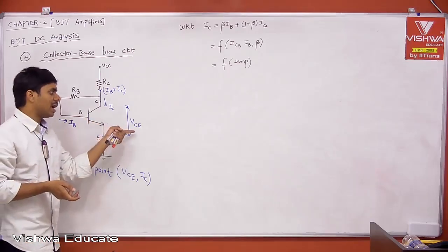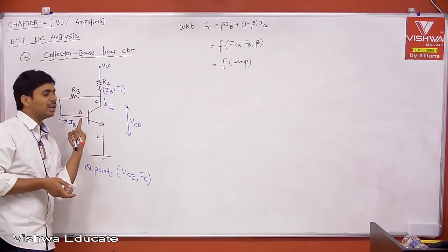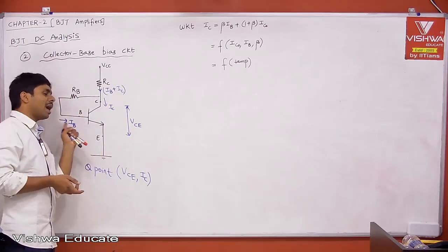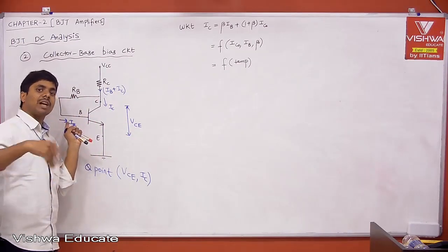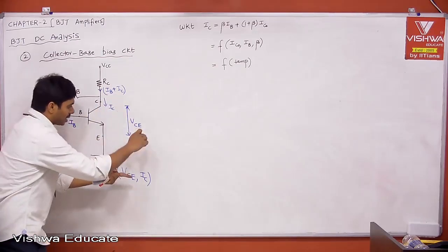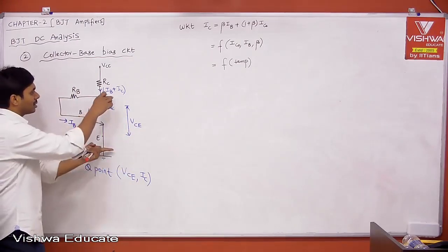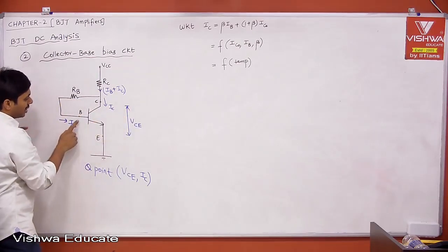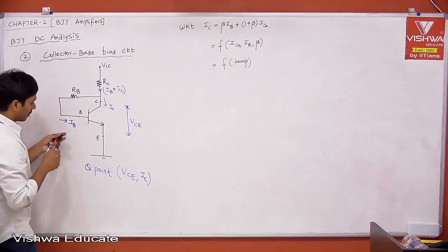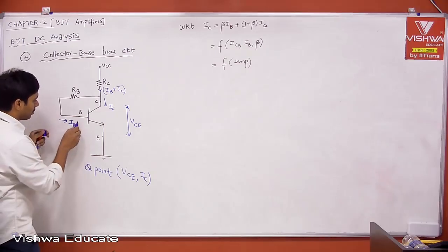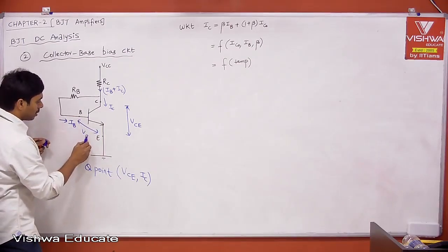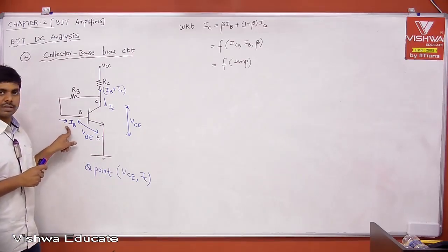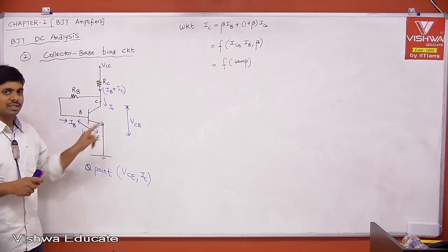That is what is called self-bias. Therefore, the voltage you are getting, that itself is biasing your input voltage, right? If there is any change in output voltage which is VCE, that will be sampled and then fed back, and that itself is feedback, that itself will control. How? When VCE is decreasing, definitely your VBE will decrease, because VCE is equal to the drop across RB plus VBE, right? When VCE decreases, definitely your VBE will decrease. When VBE decreases, surely IB will decrease.